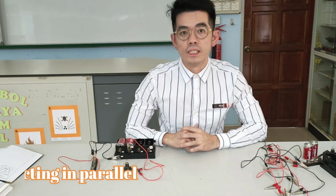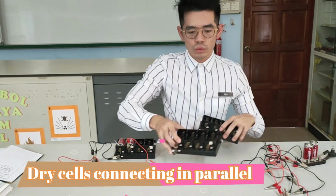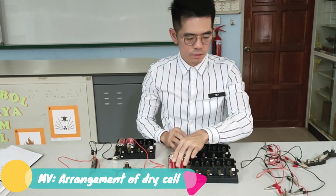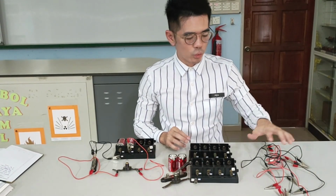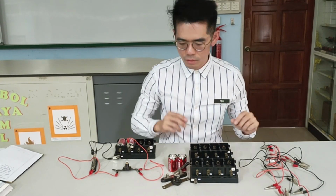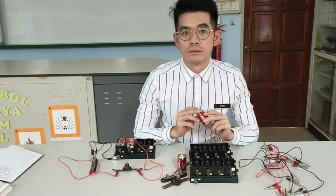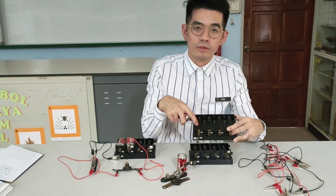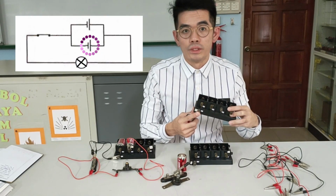For connecting the dry cells in parallel circuits, you need 2 dry cell holders, 2 batteries, 1 switch, 1 bulb, and the wire with crocodile clips. For batteries connected in parallel, again make sure you place your battery at the first space of the dry cell holder, which is together with the negative terminal of the dry cell holder.